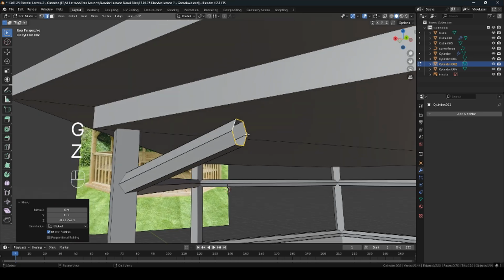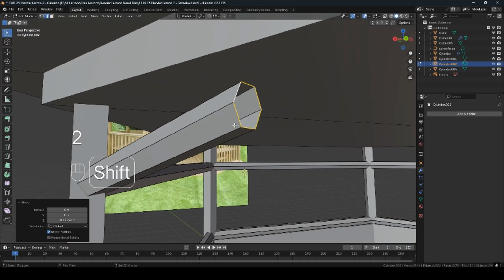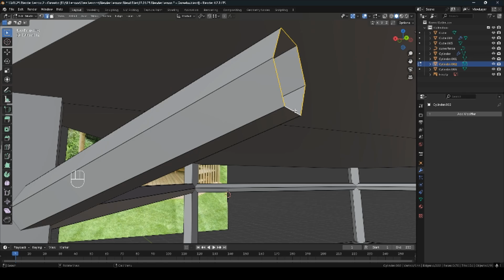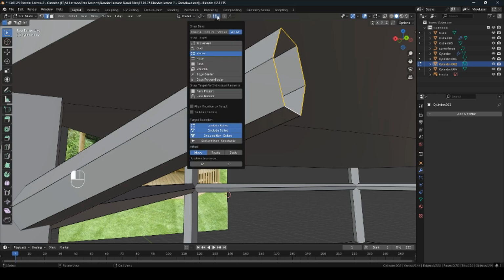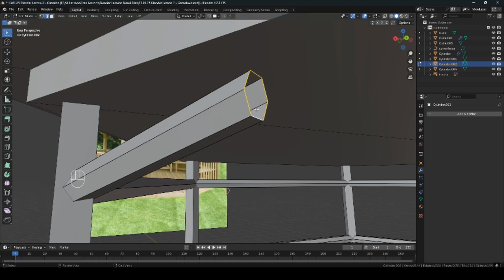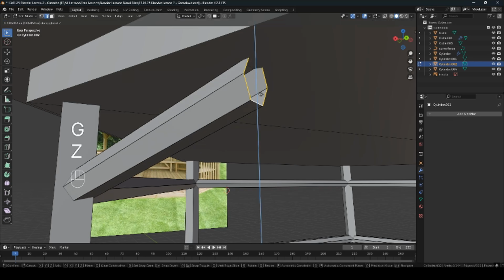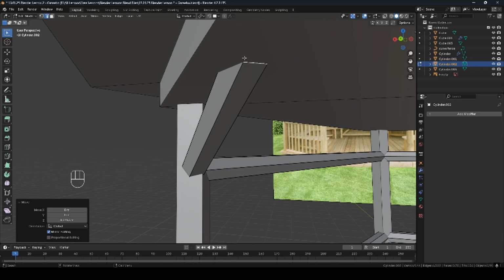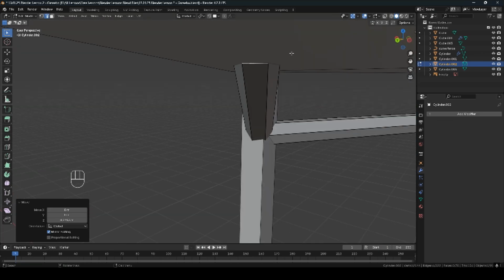So let's get it more accurate. Going back to earlier, we want to edge select our active. So this is our active, as it's white, the yellow or orange is our other selection. Up here, we want to make sure our active is set, and we want to connect it to face this time. So when I press G and Z and I hold Control, you see the bottom of that active is now going to go on the face.